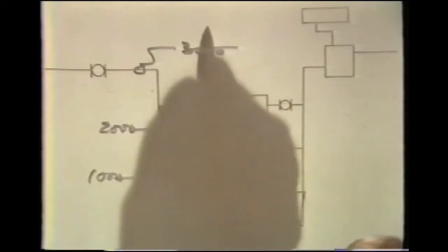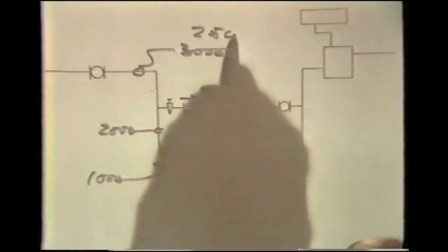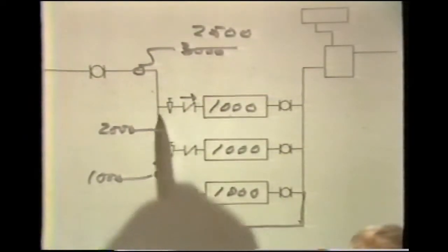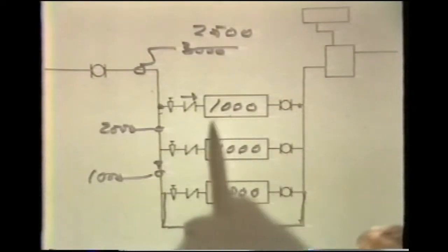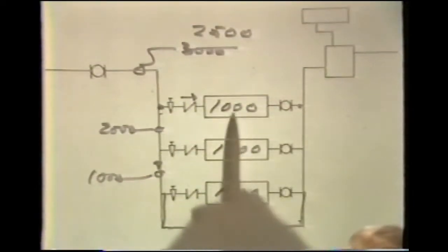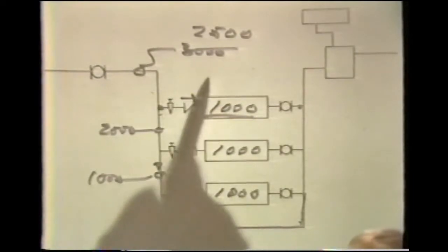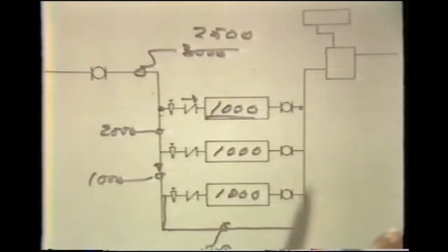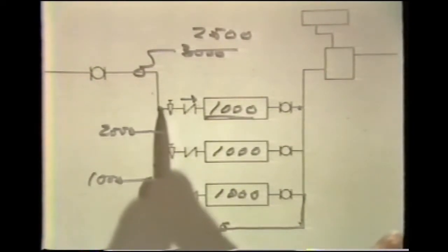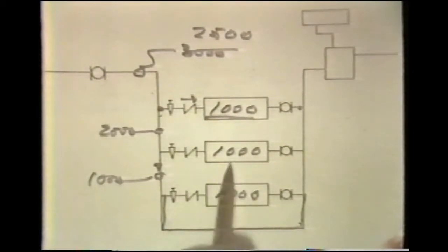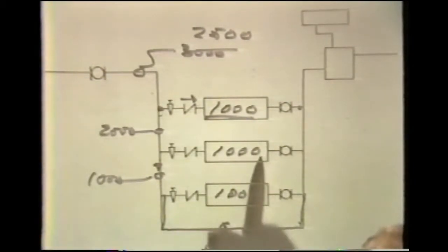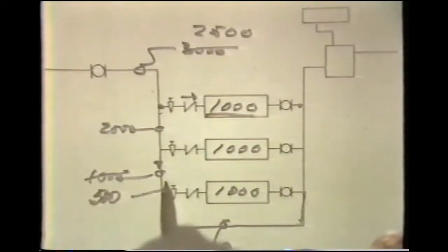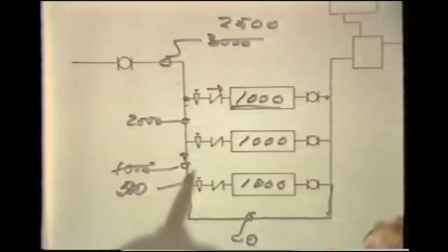Supposing now, however, that our flow rate in the distribution system decreases to 2,500 GPM. Because of the arrangement of piping, and because each of these pumps and its control and balance is set for a flow rate of 1,000 GPM, we would still drive 1,000 GPM through the first chiller. We would have 2,000 GPM available in the second chiller. We would draw 1,000 GPM through that chiller, but we now have 500 GPM available for flow through the third chiller.